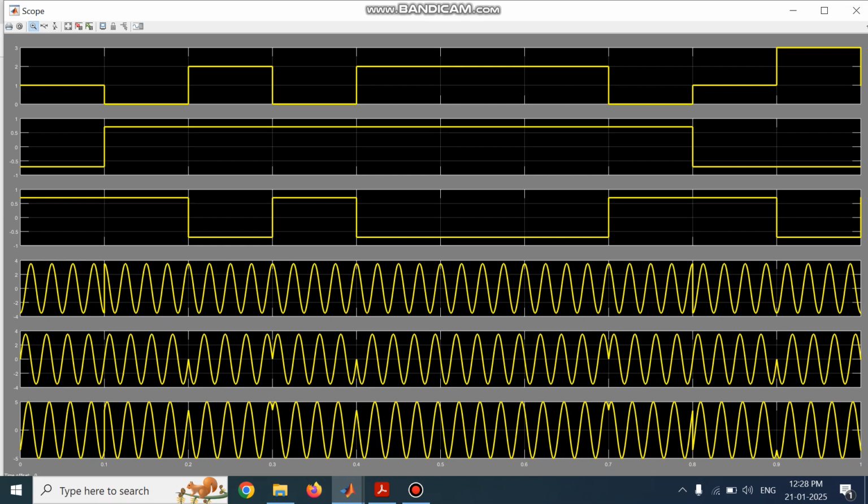Next integer is 2. To understand this, we have to refer to our previous table. For this 2, the corresponding gray encoded values are 1, 0. So 1 is the odd bit, 0 is the even bit. Next it is integer 0, so 1, 1. Next again it is 2. For 2, the corresponding gray encoded values are 1, 0. Next it is 1, 0. Next 1, 0. Next 1, 1. Next 0, 1. And finally 0, 0. So here the integer is 3, and the corresponding gray encoded value is 0, 0.